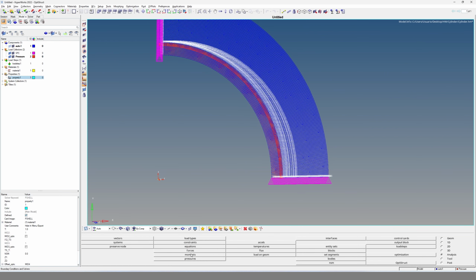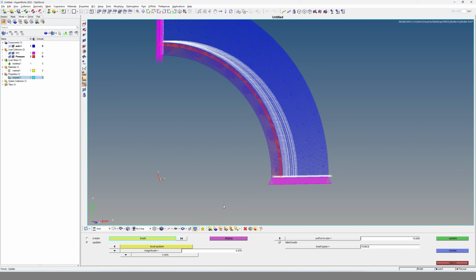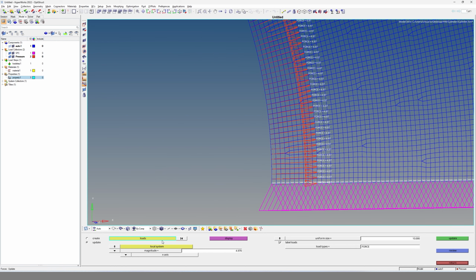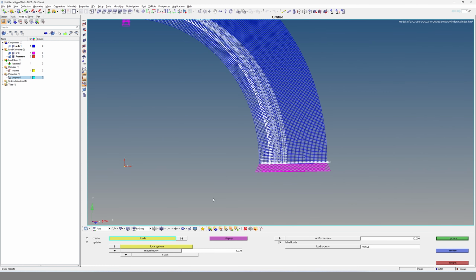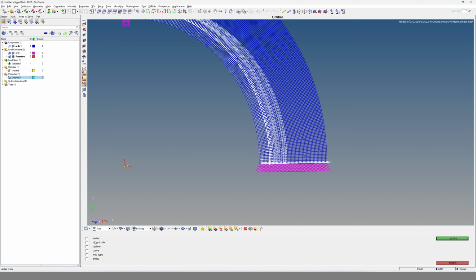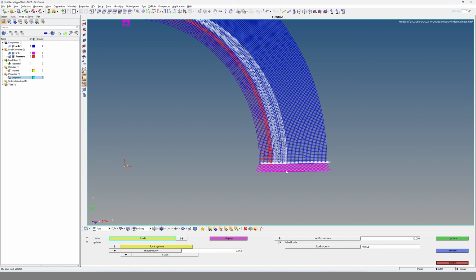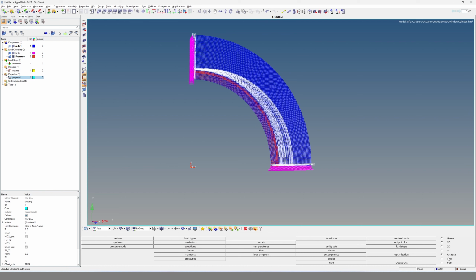For that, we should go to forces and update, and we choose the entities contained in the collector pressure, and we change its value. So instead of 4.97, it should be this value. And then we click on update magnitude. Great. Now we can run the simulation again.